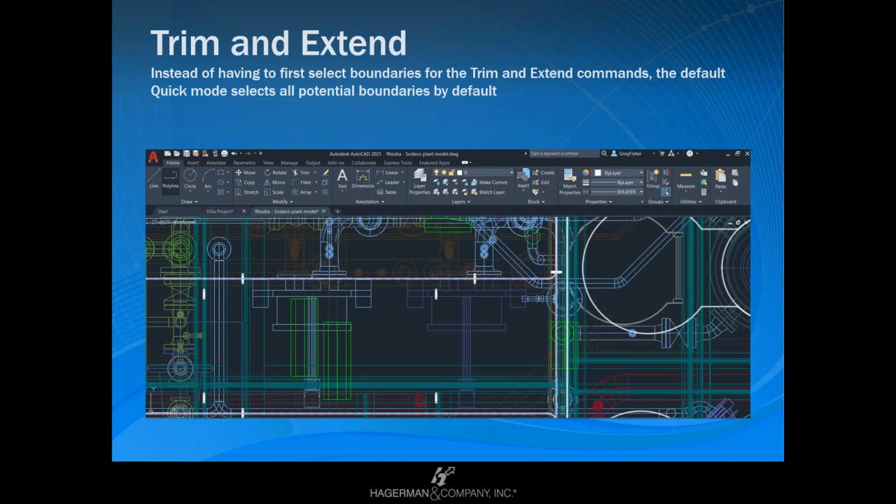It's kind of like when you go into the trim or extend command and you select everything, which I've been doing for a long time when it says select objects as far as your cutting edges or boundaries are concerned. Don't have to do that anymore. Nice part is, for you very, very experienced AutoCAD users, you can still resort back to the way that it previously worked as well. Nice thing about AutoCAD, they usually enhance and expand on commands, but they never take anything away.